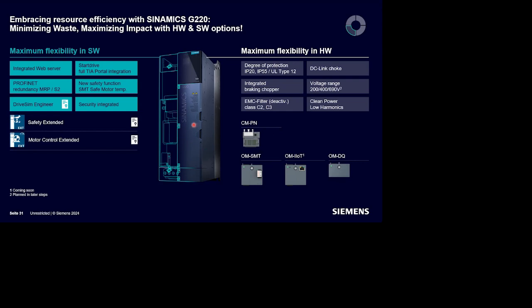On the option modules that can be plugged beneath the control unit, we have the SMT, which is, just for you to remember, the ATEX certified module for connection of the sensors of motors located in explosion areas. We have the IIoT module, which allows us to have a high frequency data transfer from the drive to the edge.